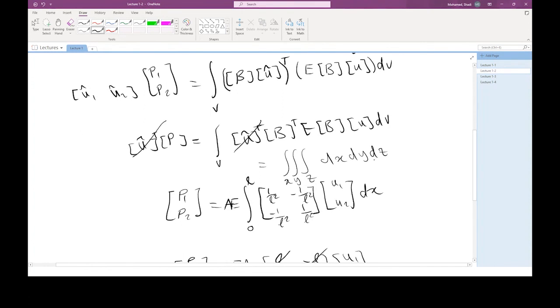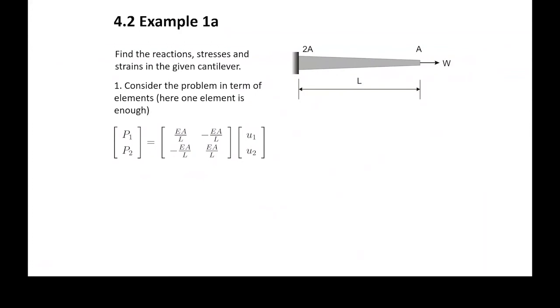And then we develop the element. And the element we develop will result in some stiffness matrix. The stiffness matrix we can use then to solve the problem. So this is one way to solve it. Can we do some other ways to solve this problem? I mean, we develop a stiffness matrix and we can solve it using the new stiffness matrix. But can we do something else? Take the average area, but then if you have the average area, what sort of information do you gain from solving the problem?